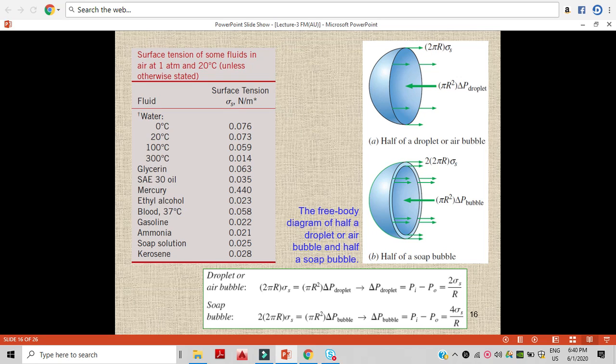It is seen in case of water droplets, water bubbles, soap bubbles. When a liquid droplet separates from the source, it takes up the shape of a sphere. Surface tension will try to minimize the surface area whereas pressure will resist this. Due to the decrease in surface area, the pressure inside the droplet increases, and it keeps on increasing until both come into equilibrium. In this manner, the droplets assume a spherical shape, which has the minimum surface area.